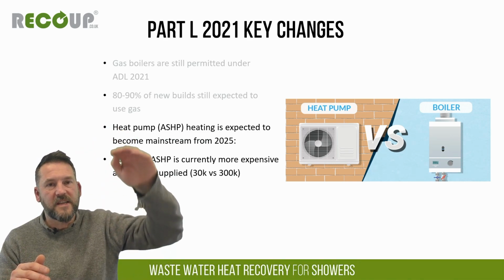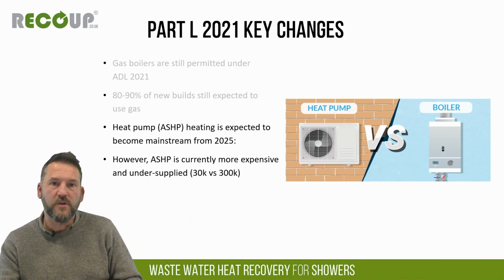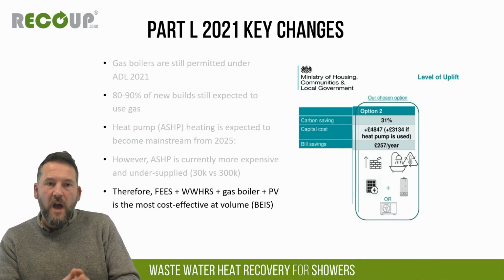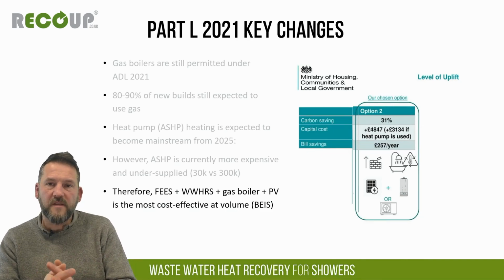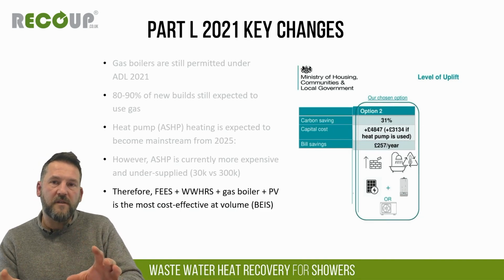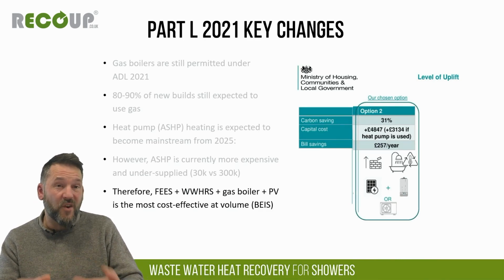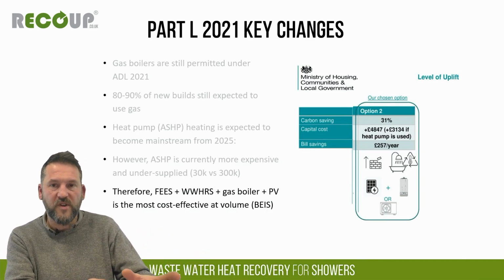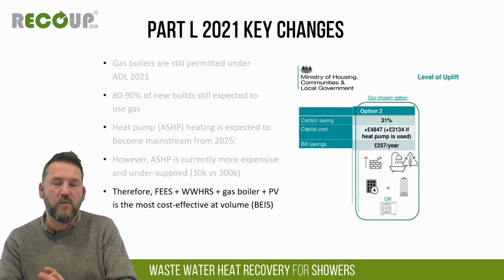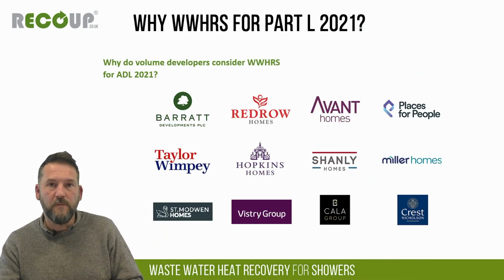seasonality and the day-to-day peaks and troughs that you get with demand through heating and hot water on air source heat pumps. So just to cover the costs, or at least where BRE see the costs for a gas boiler solution with wastewater heat recovery and PV versus an air source heat pump solution, essentially the cost for a gas boiler based system will be cheaper, and that's where realistically we're seeing that with the bigger developers at the moment, is that it's a more cost effective option for wastewater heat recovery, PV and gas boiler.